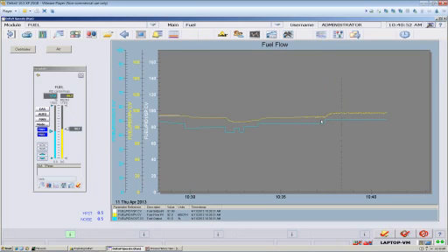is 97, okay, is about 2.5%. I've got about a 2.5% change in flow for a 3% change in output. My process gain is slightly less than 1.